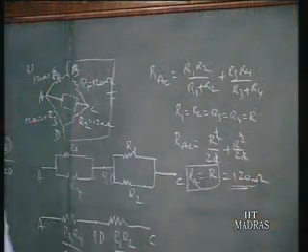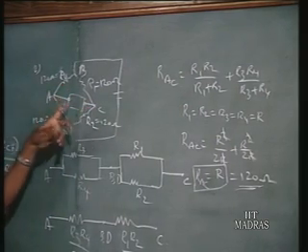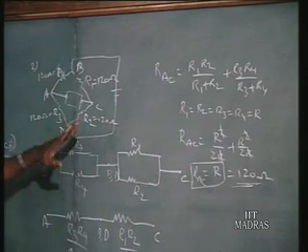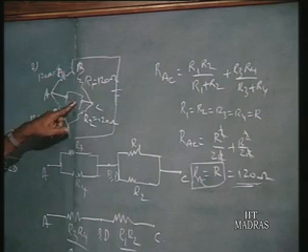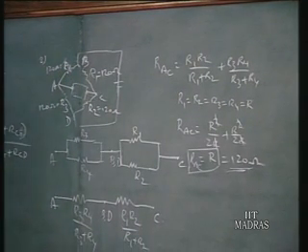Now once we know the resistance of the bridge circuit as reflected across AC, then the voltmeter should have at least 1200 ohm. That is what we have learned. The resistance of the meter should be at least 10 times the existing resistance or output resistance of the circuit.